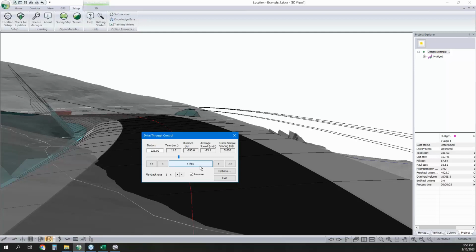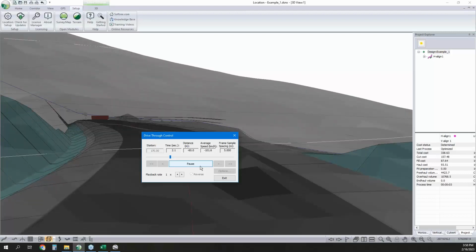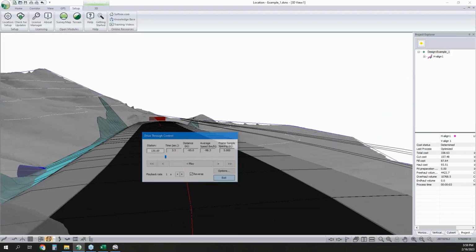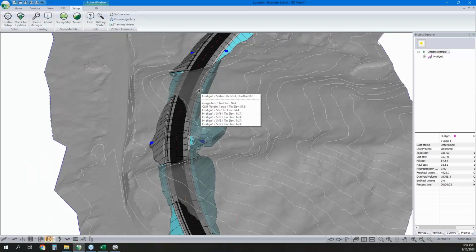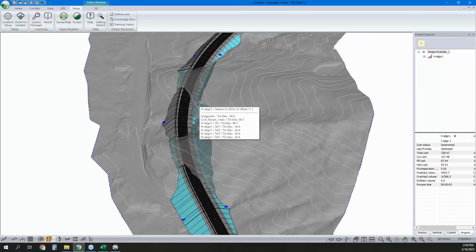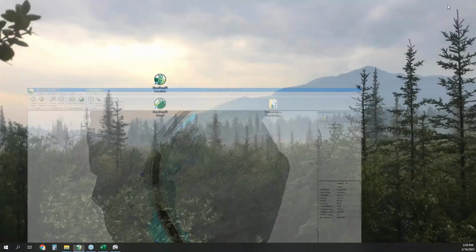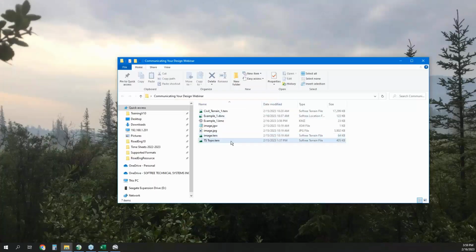And then just a follow-up to that, this one has obviously the cut being shown. Are we able to show that finished road without the shading through that? I assume that is what they are asking. Okay, you can. For that though, you'd want to export your road to a terrain file, and you'd want to merge that into your surface. So right now we're treating these as different surfaces. You would want to do a merge function here, and it's not really set up for that, but yeah,